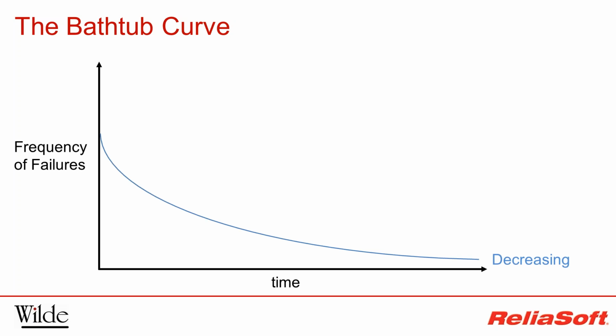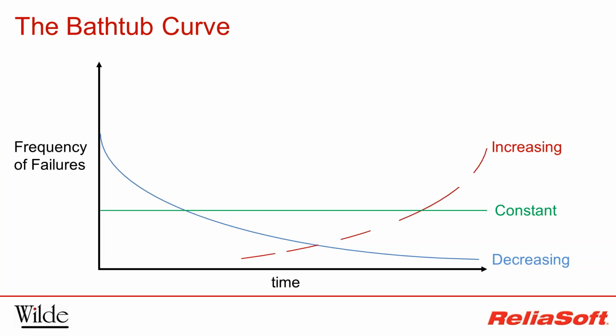Firstly, a decreasing failure rate represents an issue that occurs less as time progresses. This is typical of early life issues that arise from things such as weak design, assembly errors, damaged components, poor joints and connections, dirt and contamination. Next, a constant failure rate is typical of random failures that are an indication of operating stresses, poor maintenance, operator abuse, and accidents. Finally, an increasing failure rate is a sign of wear-out failures.